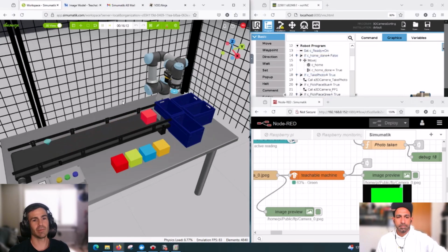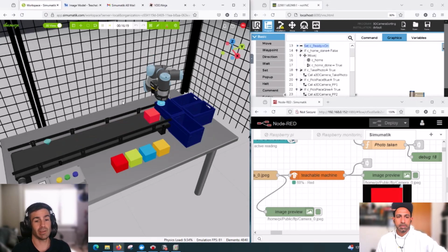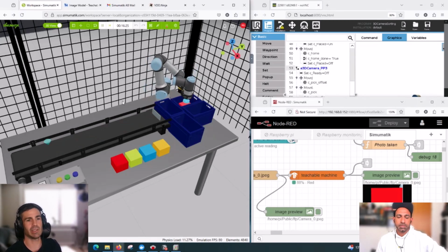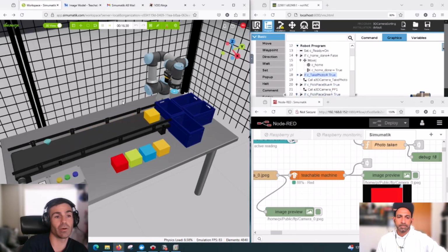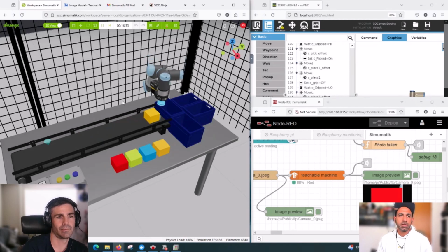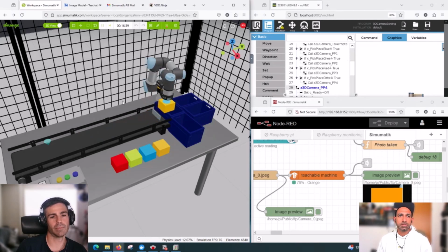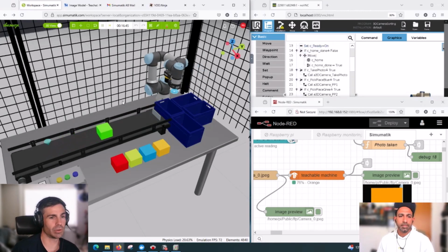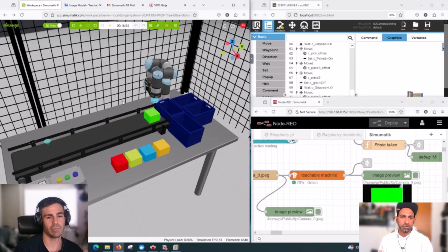But we can see more and more that the manufacturers are developing this kind of web-based HMIs, or serving them through HTML. CODESYS has been doing it a very long time ago. I think other manufacturers too. There is another one, Smart HMI. They also do web-based HMIs. And PLCnext also has web-based visualization, so from Phoenix Contact. Yeah, so I think it's gonna be more common, and we want to be able to show that. I mean, you can also do SCADA screens. They are also HTML-based, so you can run a SCADA software inside.